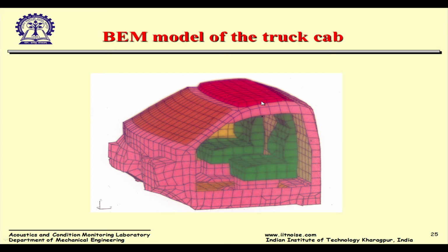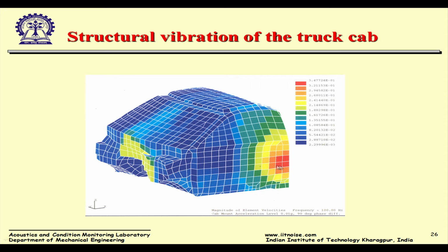We can now apply different material properties to this model. For example, your floor could have a certain carpet, your glass could have a certain impedance, the headliner could have a certain impedance, and then you have a boundary element model. By the way, this is the standard procedure nowadays in industry. And this is from the Nastran analysis.